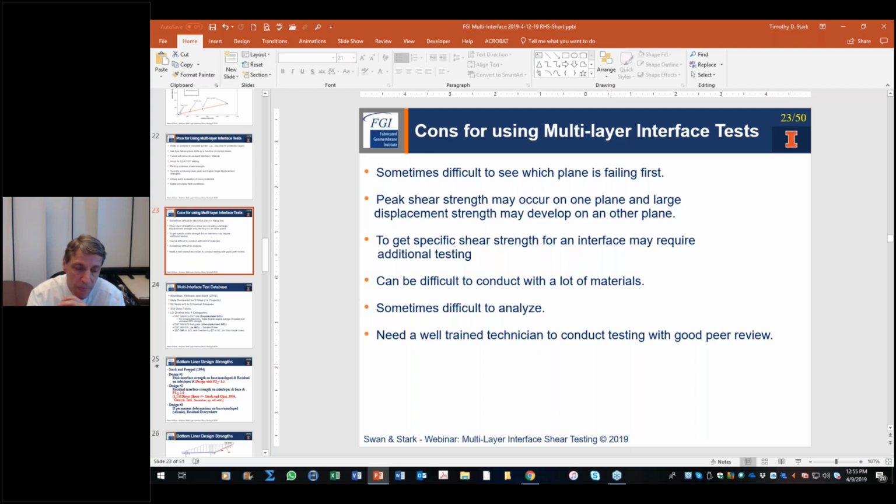Maybe what we'll have to do is have you clarify that to Rahul offline with an email. But if it's just geosynthetic, probably not. If it's, say, hydrated bentonite or a high moisture content subgrade or compacted soil liner, maybe there's some consolidation and you can gain some strength that way. But in general, the geosynthetics are damaged at large displacement and they don't heal. Sure. Okay, that makes sense.